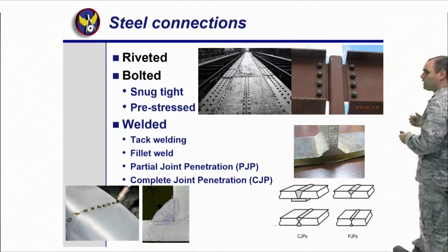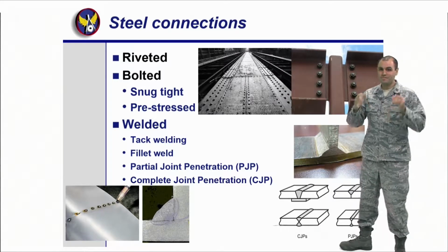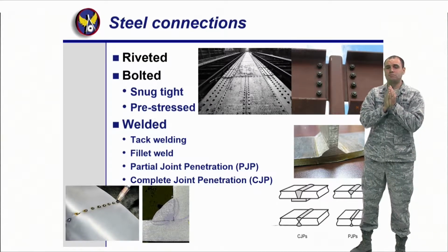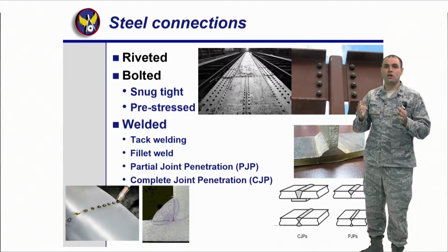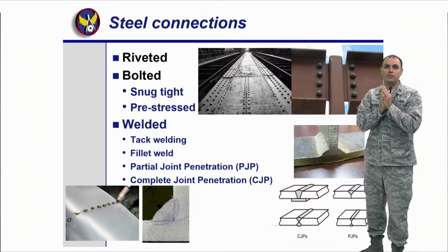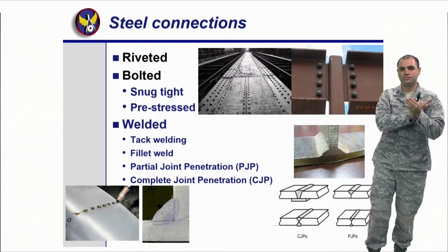Apologize for that. One whole turn to two whole turns, and I'm going to squish that guy together. What is the pre-stress trying to do? It's trying to make it seem like there's not a hole by squishing the material together and making the transition seamless, right?